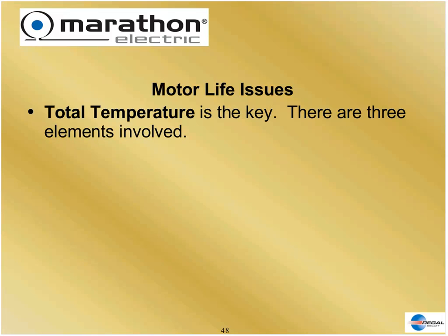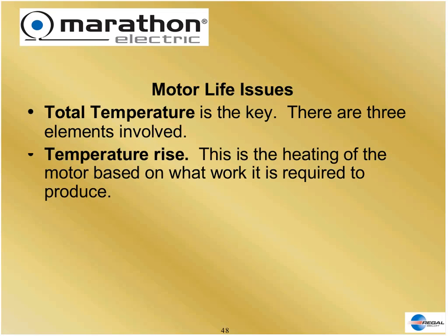So it's the total temperature that the insulation system cares about. Doesn't care where the heat comes from. Just knows that if you get too hot, I'm going to fail. And there are 3 elements typically we deal with in the motor issues. First one is the temperature rise. Temperature rise is the heat that the motor produces to do its job.